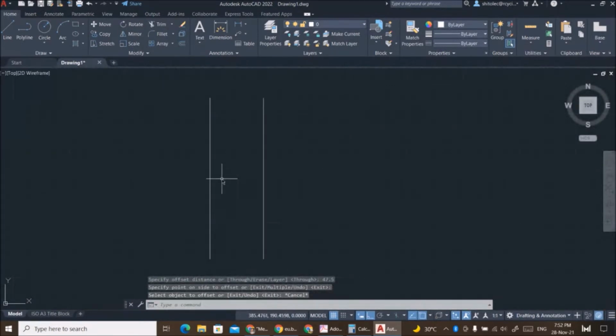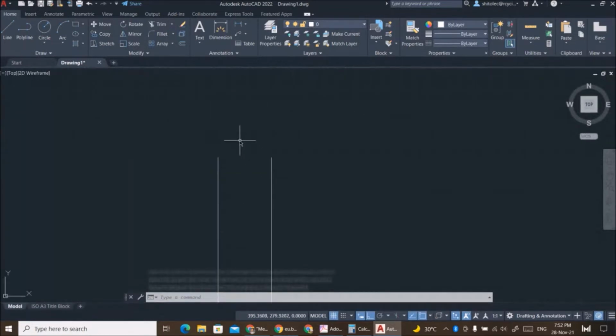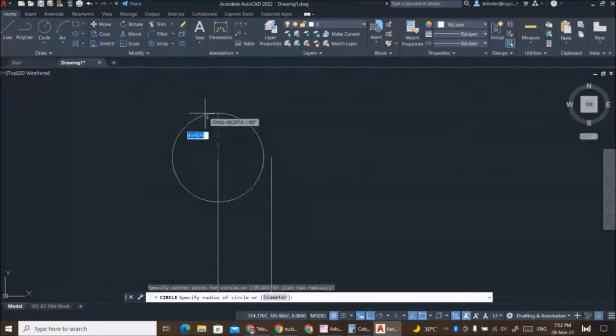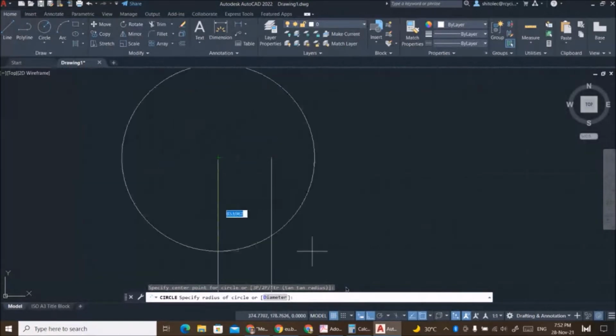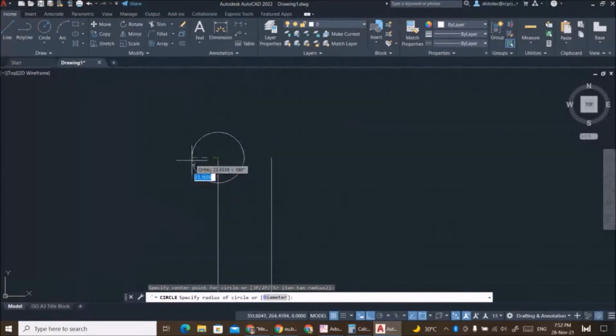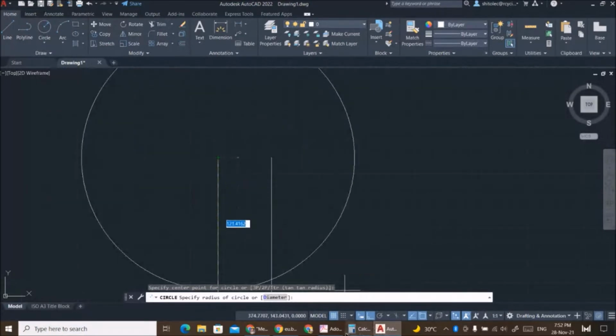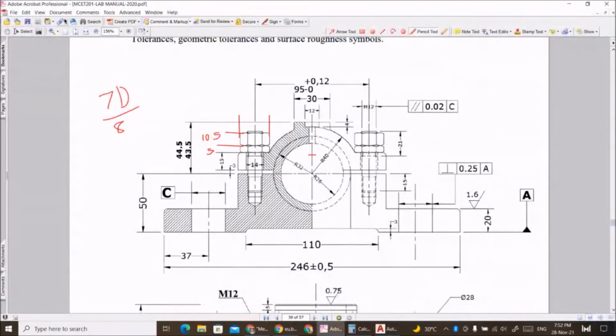Now here I will draw the screw, nut and bolt stud. So construction is as usual in lab exercise 2.3. I need to draw the circle with the radius as W. So this is M12. Small d is 0.85 of capital D, the minor diameter; major diameter is 12.